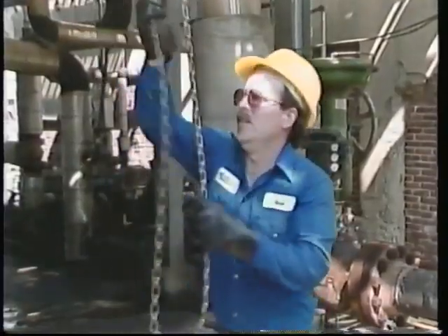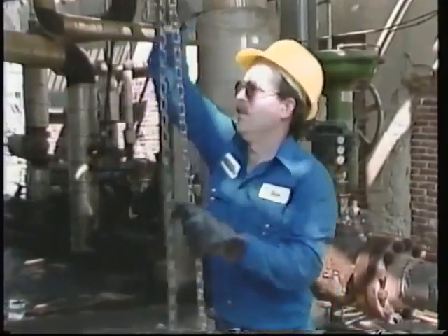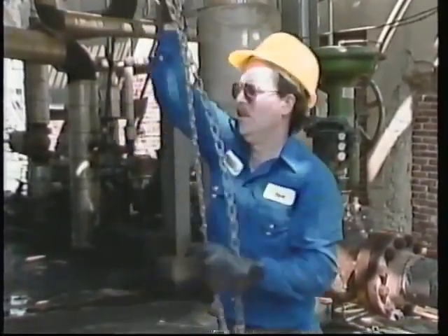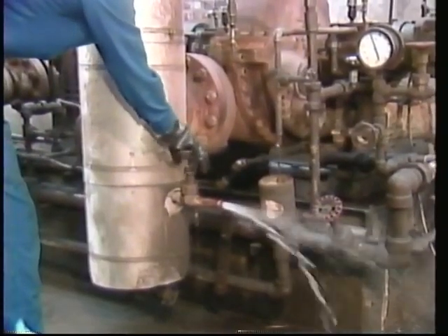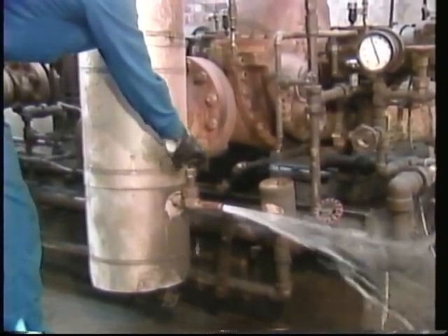After this cool-down, the operator can then completely close the throttle valve. He follows a similar procedure for the exhaust line. He closes the exhaust block valve and opens the drain valve in the exhaust piping. Regardless of whether your turbines are shut down using the manual trip or not, you'll also need to take care of any auxiliaries that require shutdown attention. This may include cutting off the cooling water system or turning on an auxiliary oil pump for a lubrication system.